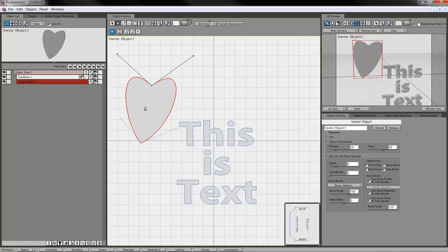There's the item, but if I draw inside of this, so if I do the same again, if I click and drag here, and then click and drag here, and then again click and drag here, and I'm going to hold my Alt key and break those handles again. Break that handle, and break the one at the bottom. Okay. Notice that it's created a hole inside the original item.